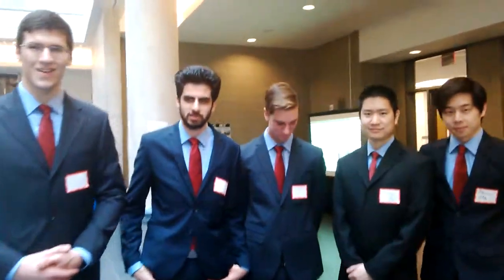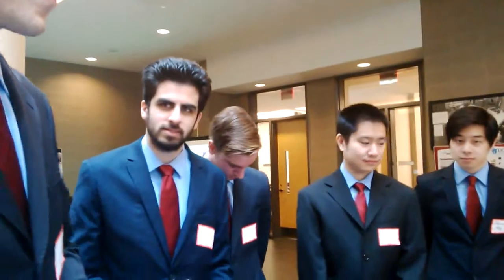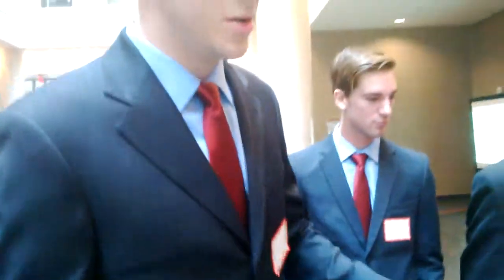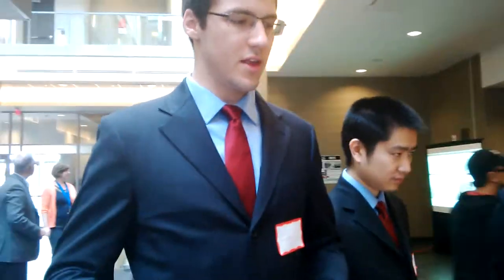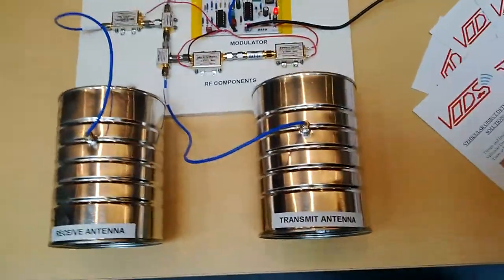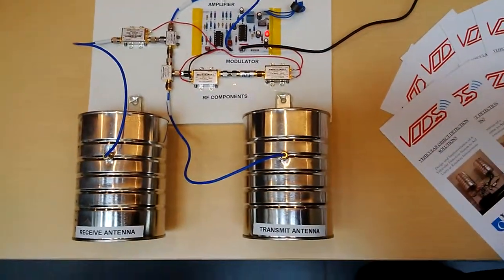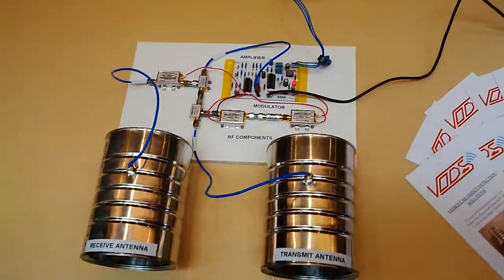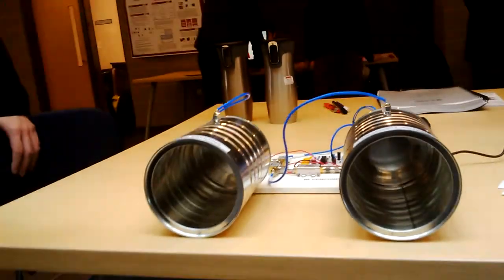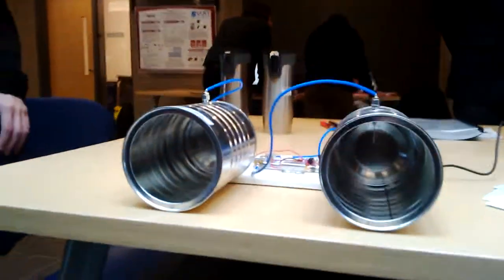All right, so help me understand what you've built so far for the capstone project here. Okay, so for our capstone project, we've built this radar front end, which is to be attached to the front of a vehicle. The intent is that it will scan an intersection as the vehicle approaches for any obstructions or other objects, so users can bypass an intersection if there's no obstructions or other vehicles. It does that by using frequency modulated continuous wave radar.